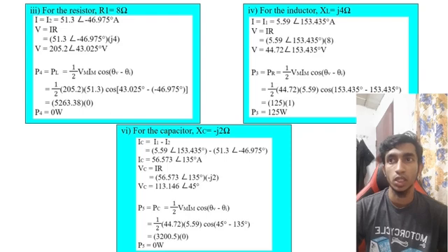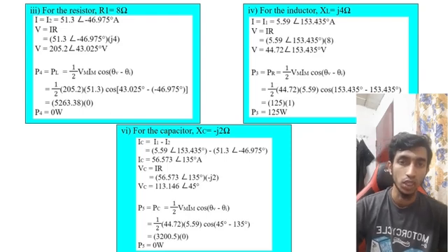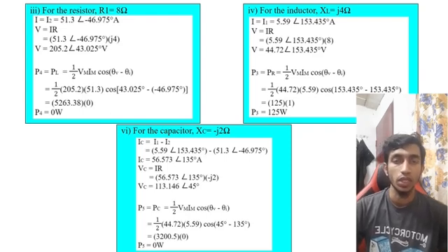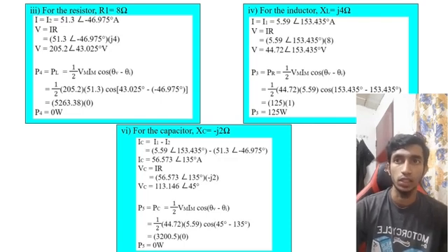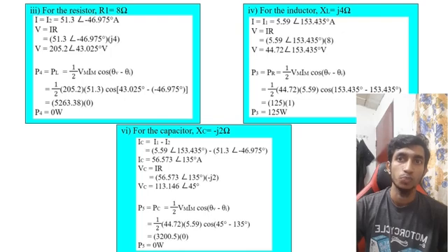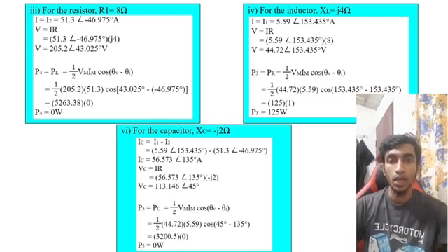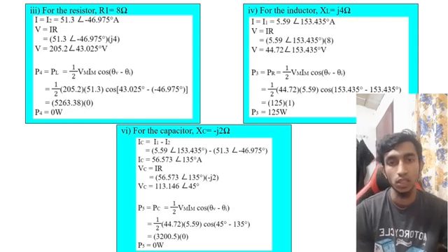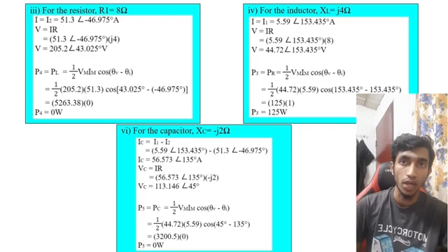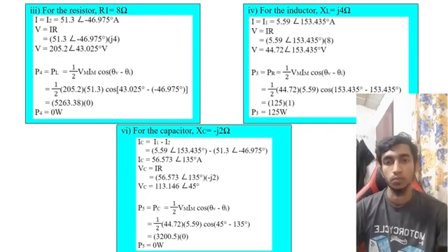The purely reactive network operates in a mode in which it stores energy over one part of the period and releases it over another. Therefore, the average power absorbed is 0 and some of the power values are negative. That is because a negative value means that the coil is returning the stored energy back to the supply.